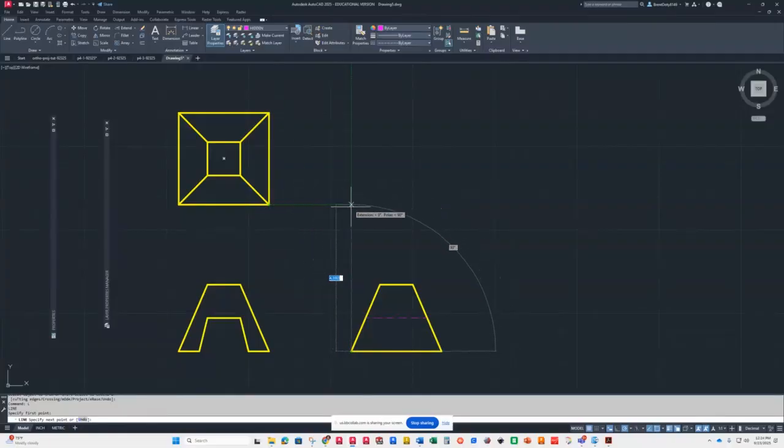I haven't been able to use her method very well, and I have to go out of my way to make it work, and so I don't use it. As long as this line and the line here line up, it will work, and you'll have your miter line at 45 degrees there. So I can draw my line from here up and over. If I wanted to do the back, I can do the same thing. You can always mirror the back if you want to.